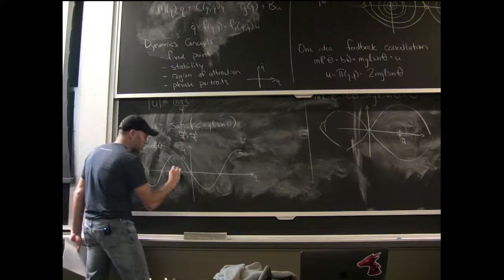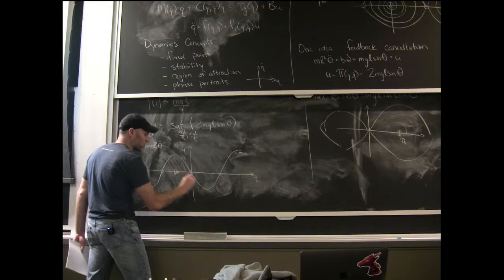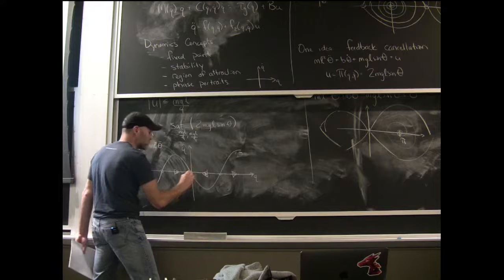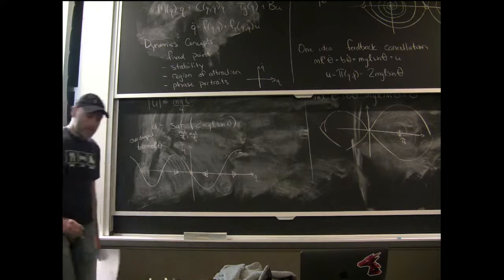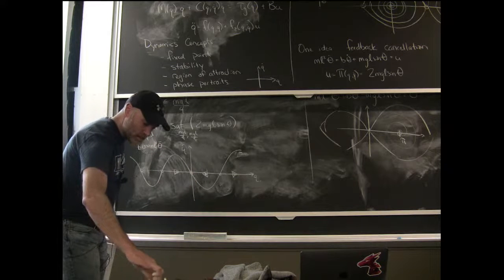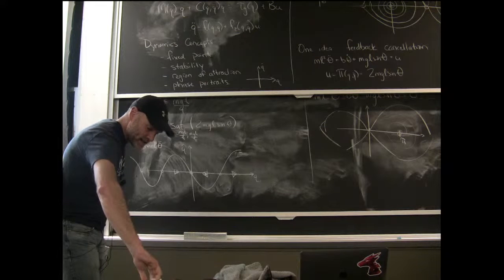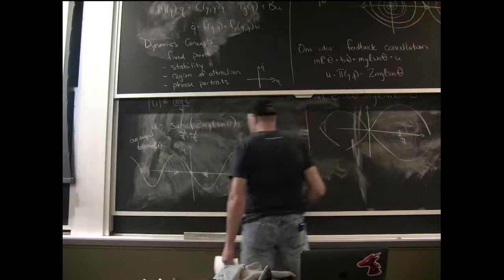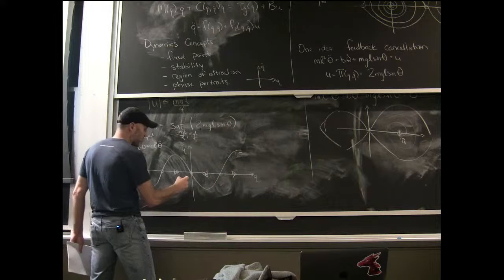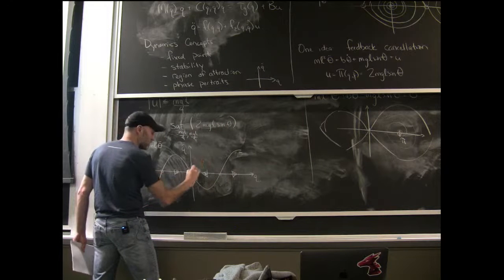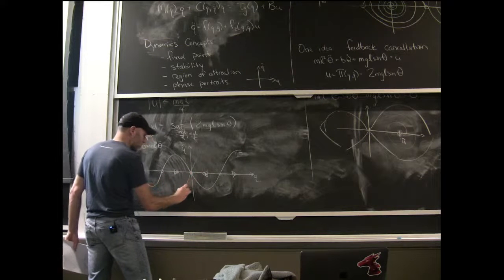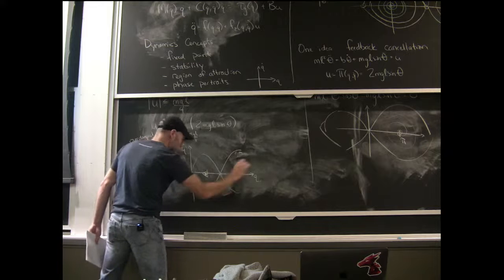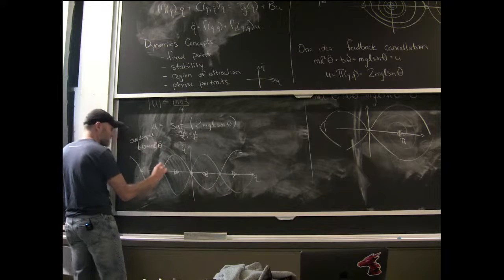Remember we did this analysis, this is going this way, this is going this way, and so on, so we know this is a stable fixed point. If I applied my complete torque canceling control, if I had all the control authority in the world, then what I've done is I've changed it to be over here. I've changed it to be like an upside down pendulum.